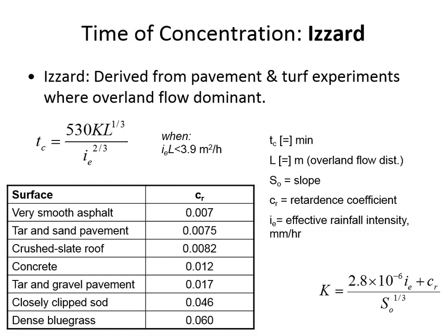And so it's sort of an indirect way of taking into account the factors that are in some of the other methods. Let me give you a handout that has a variety of these different methods mentioned. And in the homework assignment that you've got due on Tuesday, I ask you, for the parking lot that's next to the engineering building, to try applying a couple of these different methods to calculate the time of concentration. So there's the methods themselves.